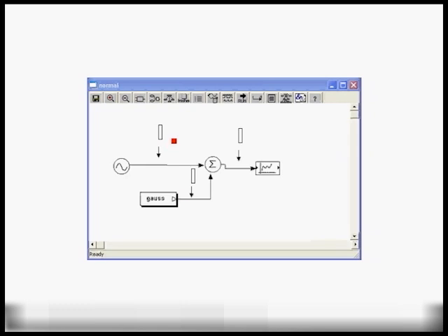In this diagram, we show a simple topology in which we have a sinusoidal generator over here, we have an adder, and another source block called Gauss, which generates samples with a Gaussian normal distribution. And over here we have a block that plots the samples. Now in a Capsim simulation, what happens is that the simulation kernel schedules these blocks for execution, and it also has a special consideration for source blocks like the sine wave generator here and the Gauss wave generator over here.